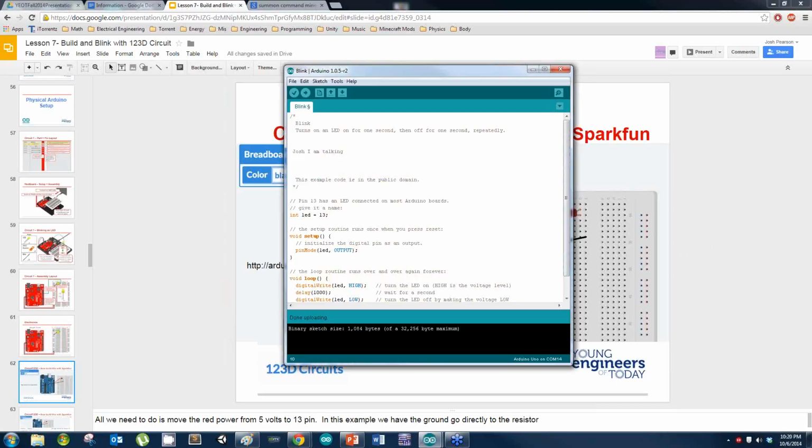All right, somebody else said something. Mine blinked for a while, then it stopped. Dennis, what's going on with yours? Yeah, it just started up again. You might have a loose connection. One of the wires might not be plugged in all the way, or one of your LEDs might not be in all the way.